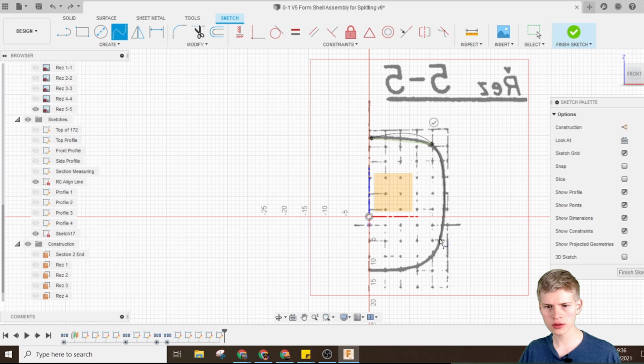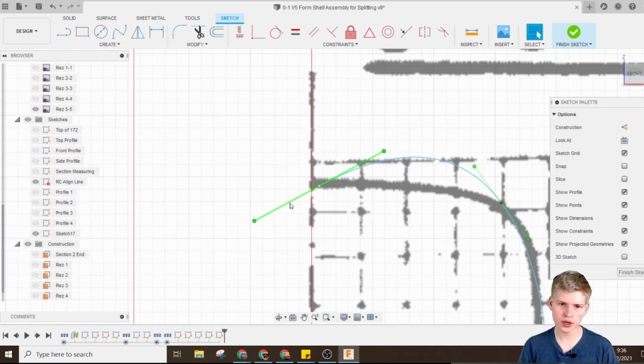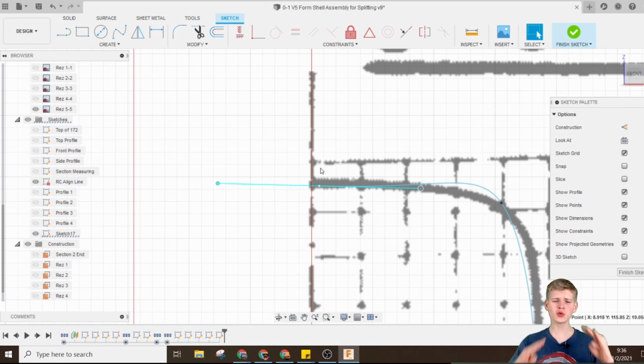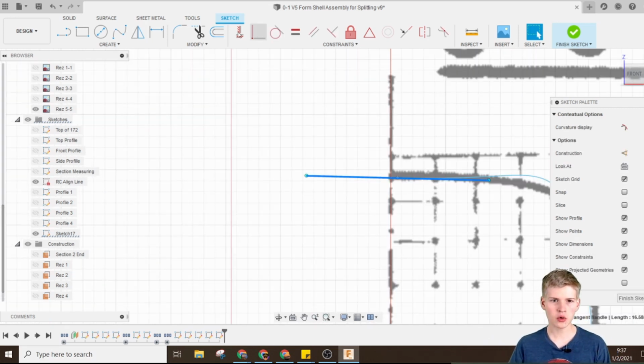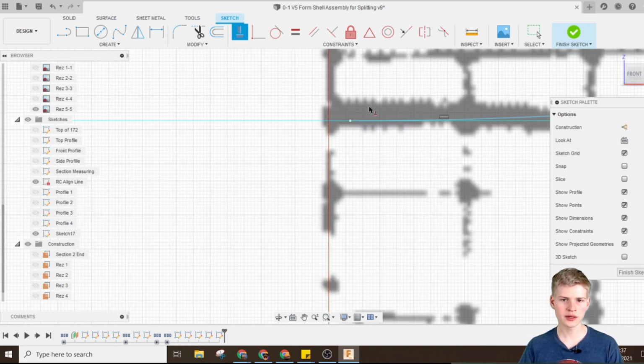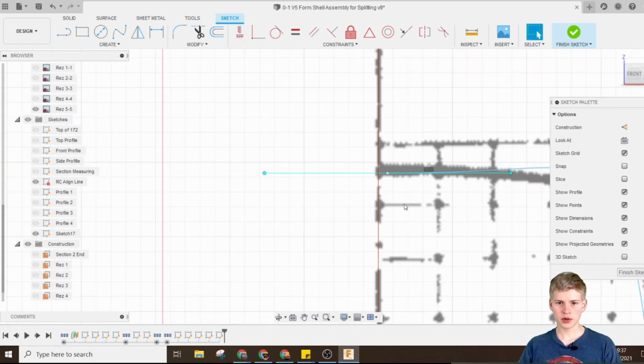I really want the handles to be horizontally constrained right here, because I don't want there to be a mountain where the two halves join together, and I certainly don't want there to be like a little divot, like a heart. I do love Cessnas, but I don't want a seam in the middle where they join together. So I'm going to horizontally constrain this line right here, and that'll make sure where they join is perfectly flat.